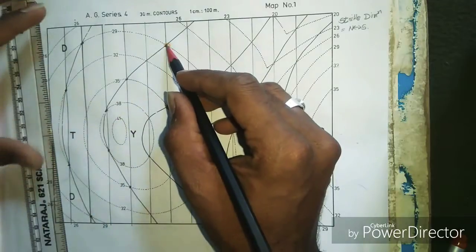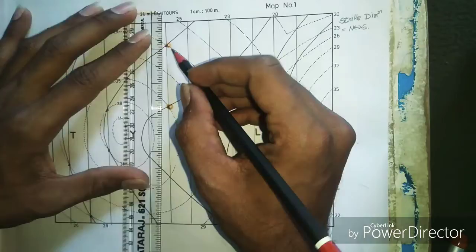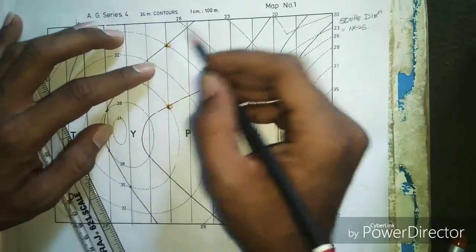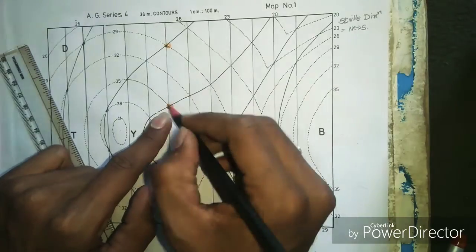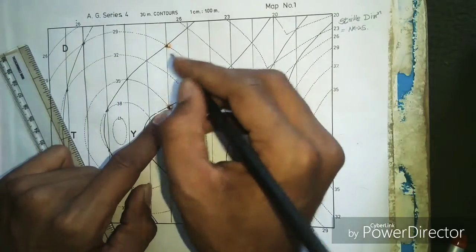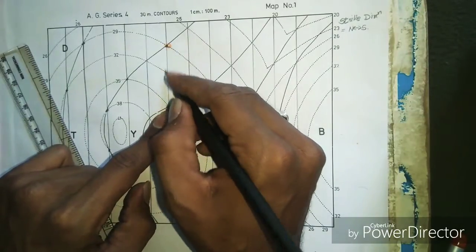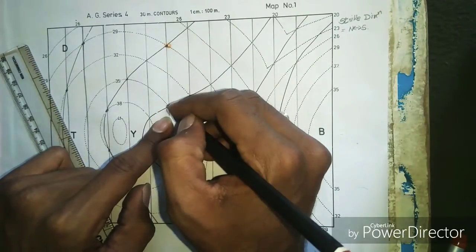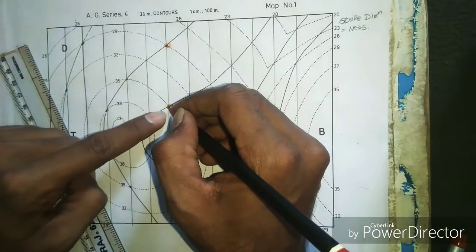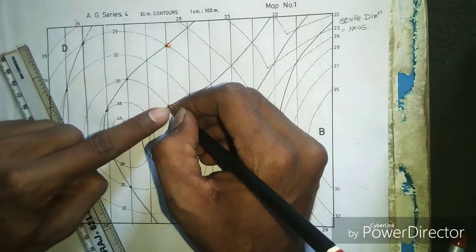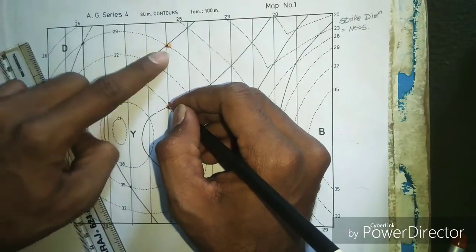So consider two triple junctions on the beds, and then measure how many contours are going from that strike line: contour 1, contour 2 and contour 3. There are 3 contour lines going from this strike line in this bed, bed Y. Then calculate: this is the contour line of 350 meter and this is the contour line of 290 meter.